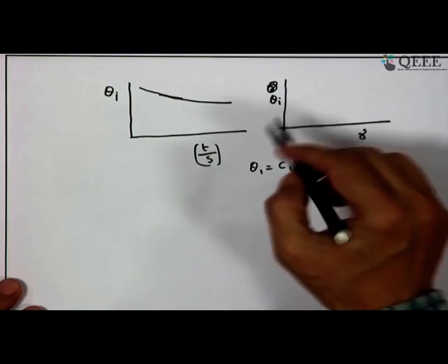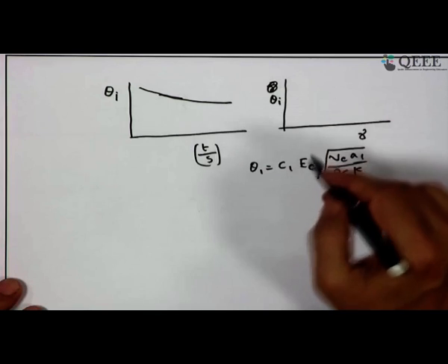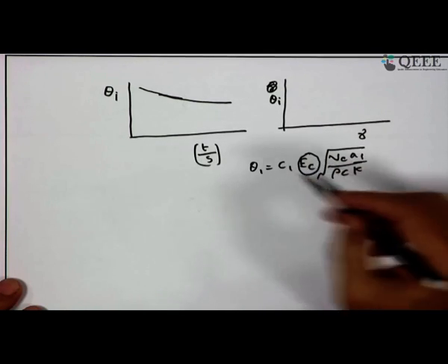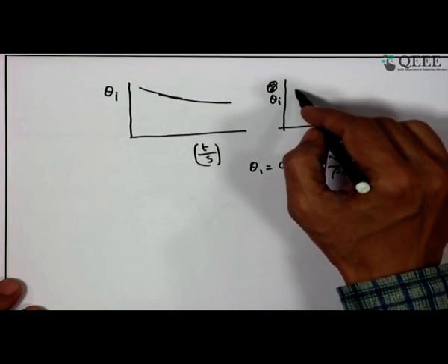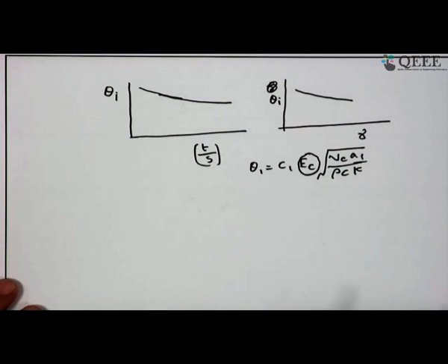Now, if I reduce the value of Pz, definitely that will influence EC, and then you have a drop. However, we have to keep in mind that too much increase of positive rake may weaken the tool. So, this is also one point to remember.